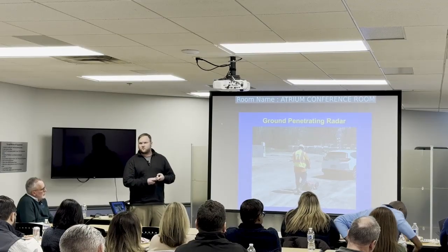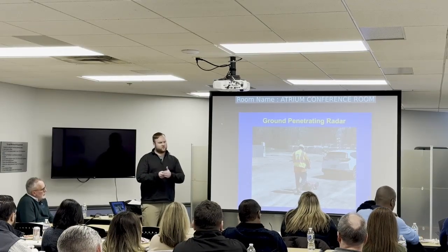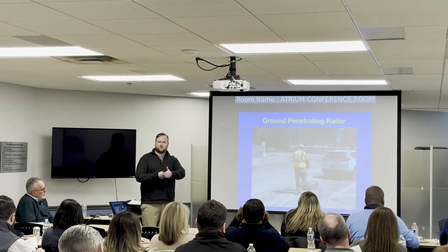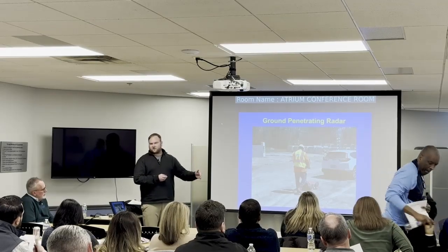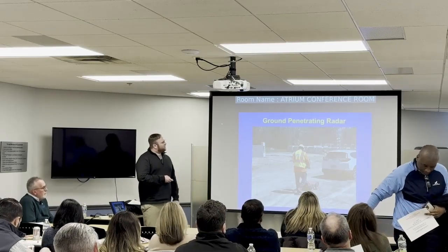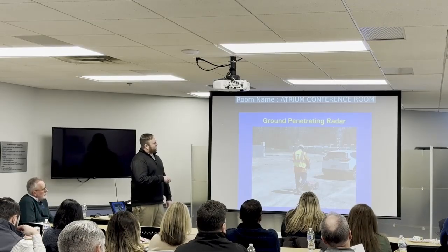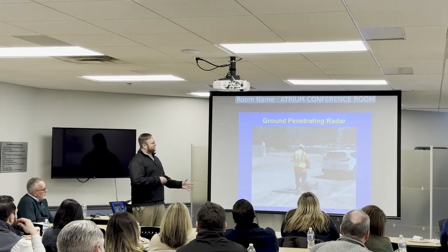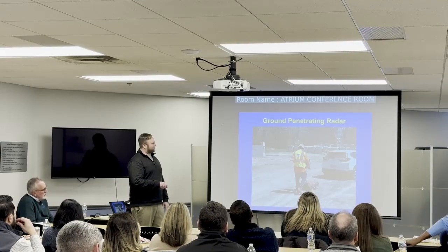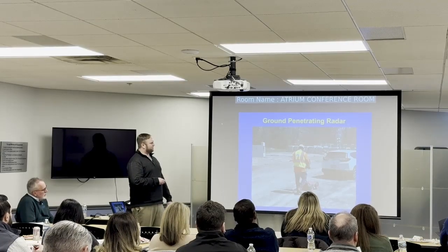You can identify differences in geology. So if it's a prior excavation, you can see the difference from native soil transition to fill. You can see metallic objects, ovular objects. Where this gentleman is scanning right now is on top of three, hopefully, 20,000 gallon heating oil tanks that existed in the 40s. He's about to find them.